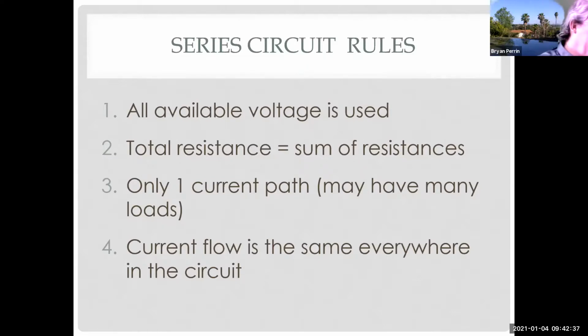Where the book, as we'll see when we get into it, talks about using an ohm meter to ohm out the injectors, why would I? That's a lot of work. That's a lot of taking things apart. I would use current, and I would use Ohm's law here to measure current on all the injectors to see if I have a problem, and I can identify which one's bad. And I'll show you how to do that as we move on in the class.